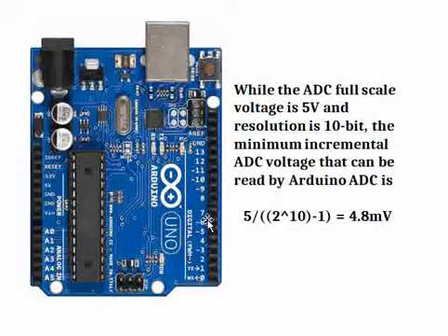When we connect external sensors and provide inputs, it is important that we know this voltage, because it tells us what kind of sensors we can connect, whether incremental inputs from a particular sensor can be read by Arduino Uno or not.